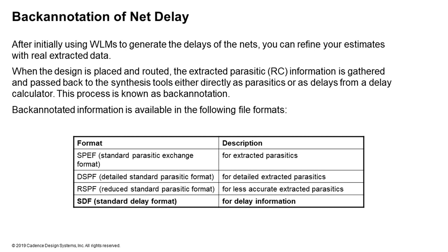This extracted data can be passed back to your synthesis tools, and this passing back is called back annotation. So you can send that information back to synthesis to get more accurate timing data for your net delays, and synthesis can now do a better job at optimizing the rest of the design based on the available information.